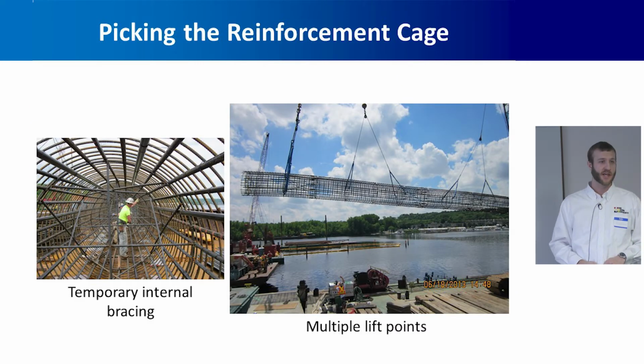Here's one of the cages at St. Croix being picked, doing it the right way. They've got some internal bracing in the cage to give it extra rigidity when they pick it, and they picked it up with multiple lift points to keep it nice and straight, and then got it in the vertical position.